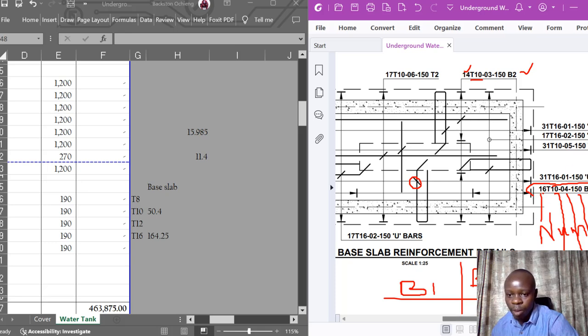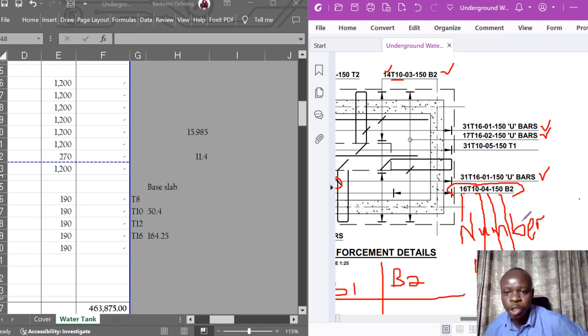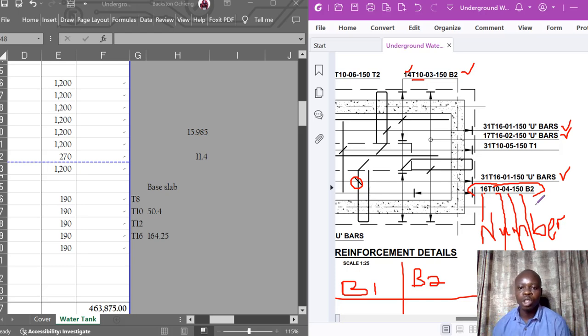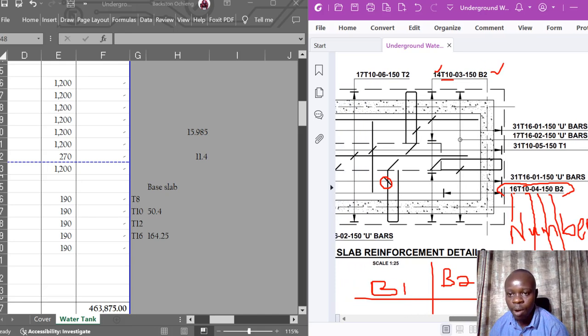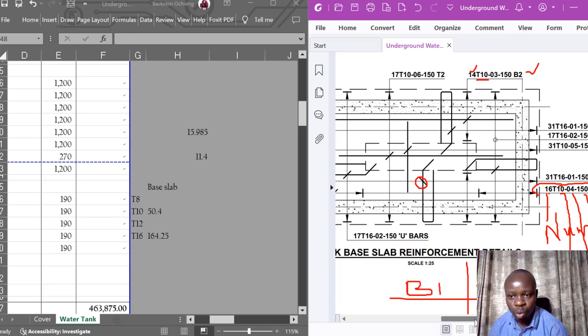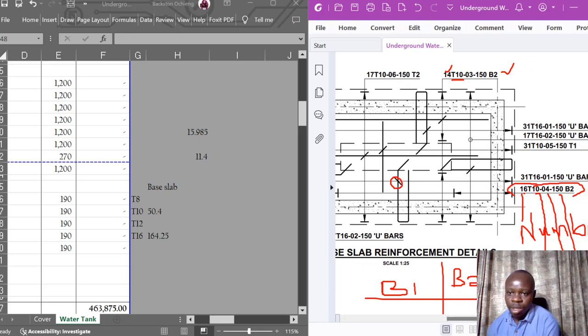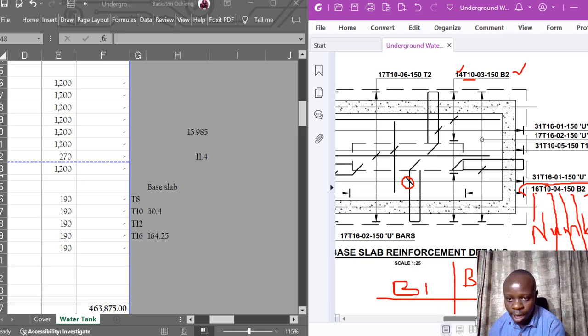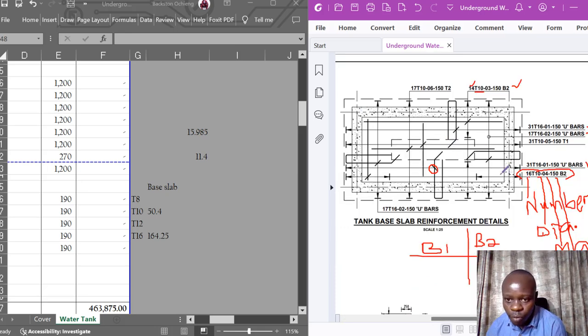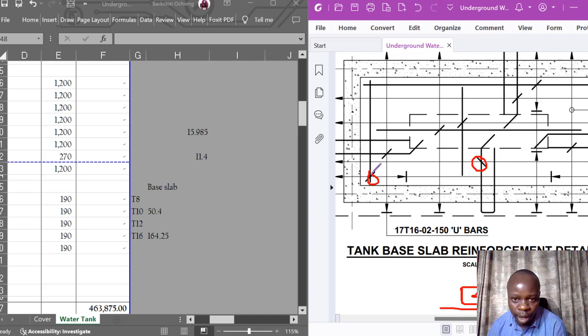I can see 4 here, the one I was using to give an elaboration. Bar mark 4 is here. Up to now you should be able to know where the reinforcement bar itself is, according to the annotation rules. So bar mark number 4 is here. This is the arrow. So you follow that arrow all the way up to here. This is where I found the reinforcement bar.